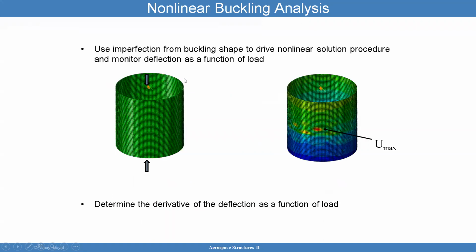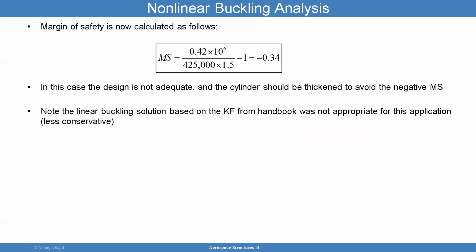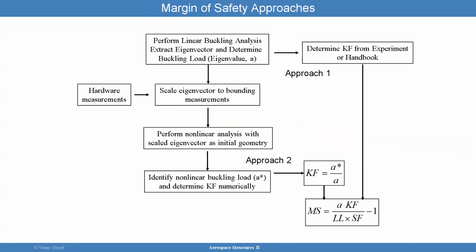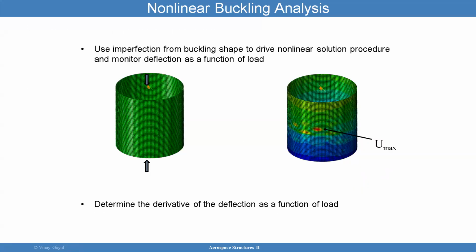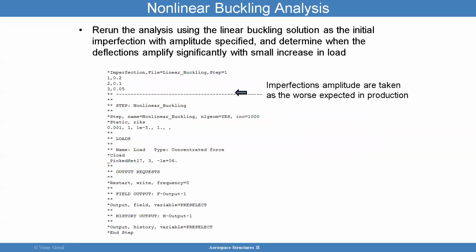If after they manufactured it, even with that drawing tolerance of 0.005, somebody came in and hit it with a hammer without realizing it, and now that amplitude is 0.2 inches, voila. I take the mode shape, which is scaled to 1, and multiply by 0.2 by adding this start imperfection command that Abaqus allows you to do.